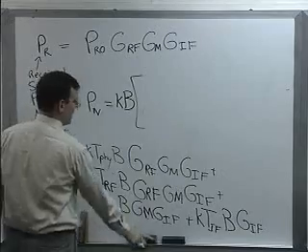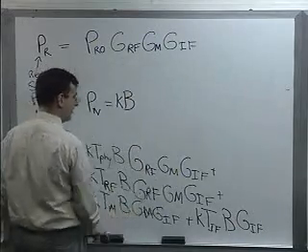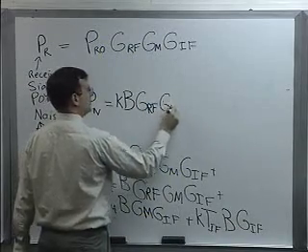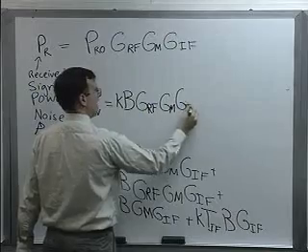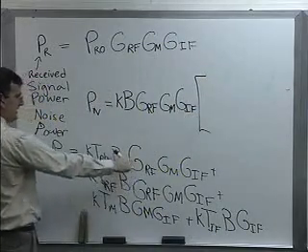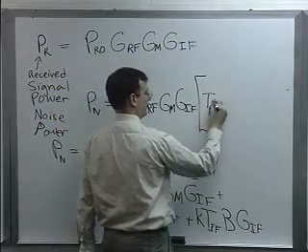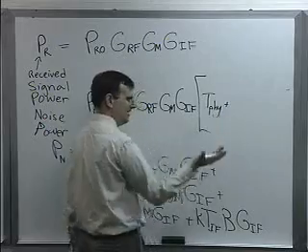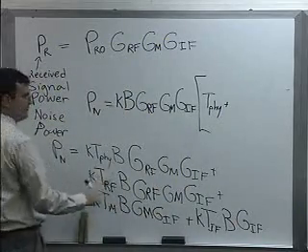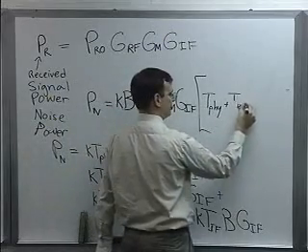But you know what? I'm going to go ahead and factor out all of our gains, too. So it looks kind of like this up here. G sub RF times G sub M times G IF. And when I factor all that out, you see what I'm left with here on the first term is a physical temperature. Makes sense? That's physical temperature of your antenna. Second term is the physical temperature of the low noise amplifier, T_RF.